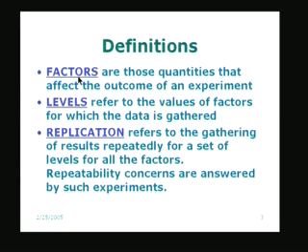In fact, I talked about 2 factors here, the speed and the depth of cut. With a given speed and a given depth of cut, I will repeat the experiment again and again with different stock or different material, or same material I may have different specimens, and I am going to vary the speed and vary the depth of cut. But in a particular experiment, I am going to keep these 2 values at fixed levels, and at those fixed levels I am going to repeat the experiment again and again.